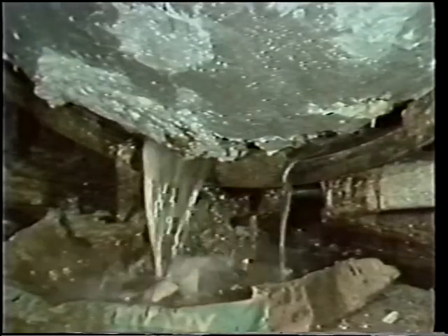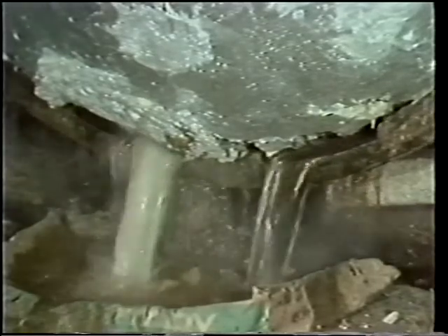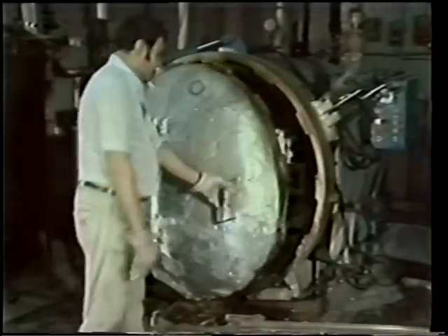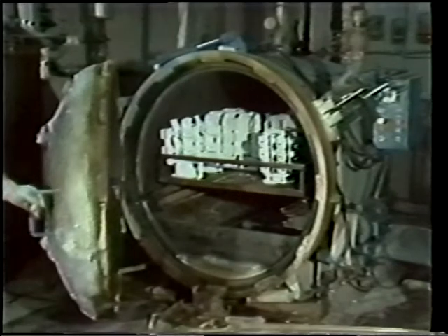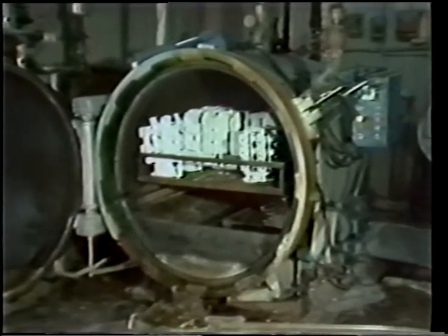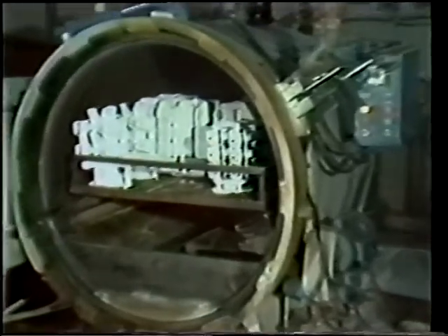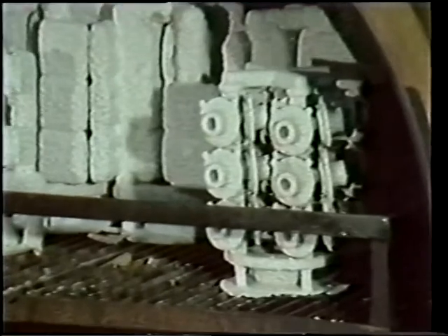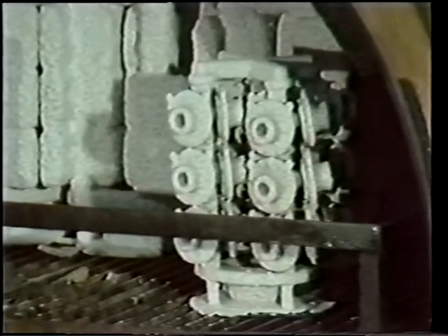A very complex pattern can therefore be removed from a mold without the mold having to be made in 2 or more sections in order to be opened. This enables more complicated shapes to be cast with the investment process than with most other processes. De-waxed molds are often fired a second time to completely remove all wax residues and to impart full strength to the ceramic mold. Some of the wax is collected in the bottom of the oven and recovered for future use.